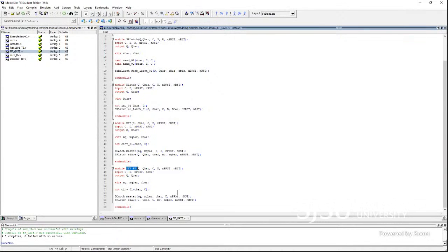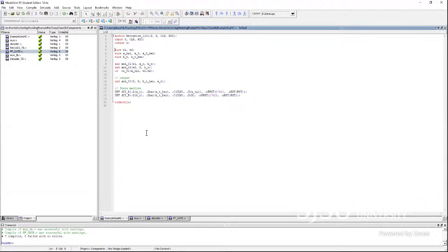That is the component I used, and its clock configuration is just opposite to that of the other flip-flop. And also, instead of positive edge preset reset, I went for a negative edge preset reset in this case. That's why I marked that name as N preset N reset in that order. But it's practically a positive edge flip-flop with a preset reset.